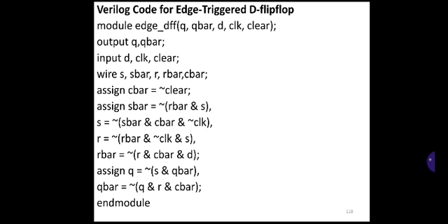So this is a NAND gate. That's why the NAND gate symbol is the tilde sign followed by the AND operation. Together it is a NAND. That's why R bar and S. So R bar and S performs the AND operation. To make it NAND, just complement it by using a tilde sign. So this is S bar.